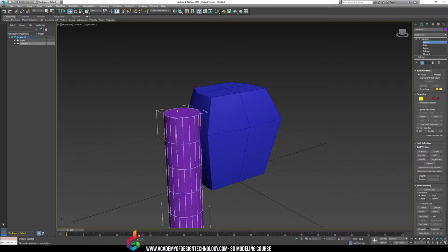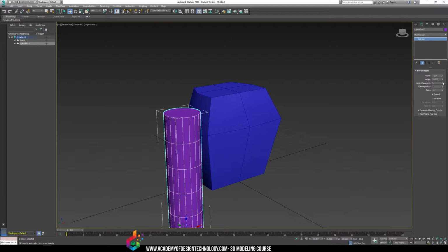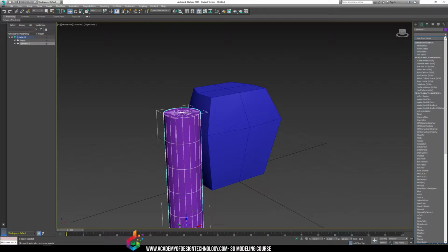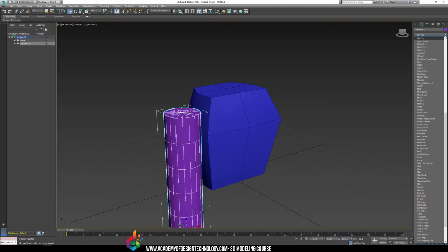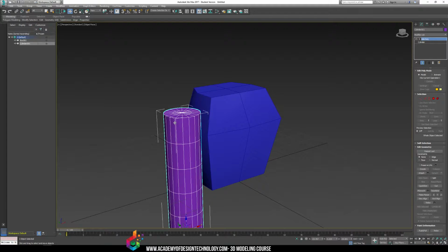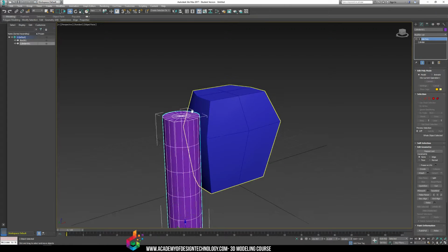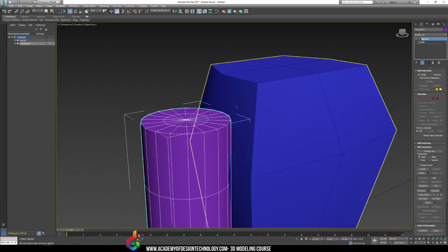Now you'll notice as we were creating objects, I'm going to back up here just 1 second. I'm going to add a cap. Remember to try and always add a cap segment until you get lines on it, visible edges, because if there's not, you'll create a bad high polygon mesh that won't work for a lot of situations. So try and create the cap segments there.